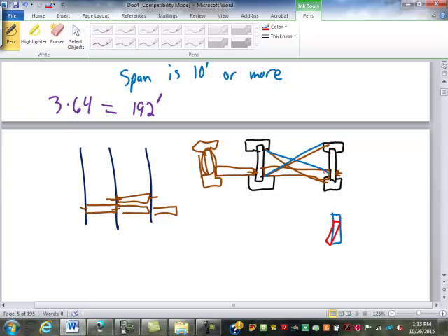So the strong back bracing makes it so that if it's going to twist, all of the joists have to start to twist. So it holds it in place. And usually it goes all the way out to the walls, where the rim joist should be nailed down to your sill and sealed down, bolted down to the top of your foundation. So it's really tough for the whole thing to move.